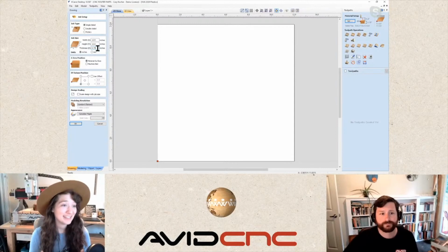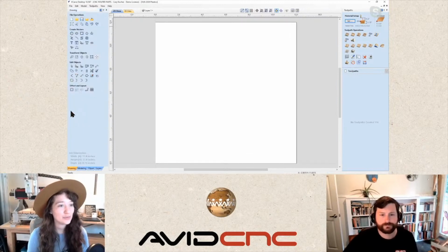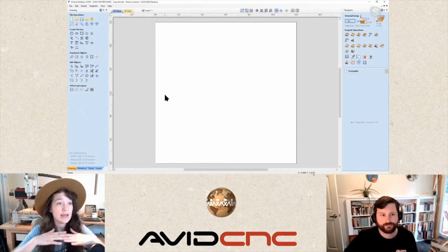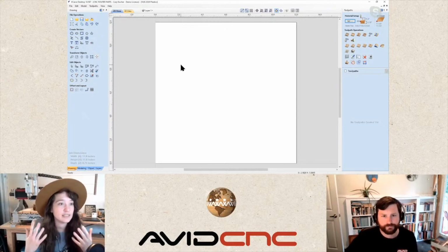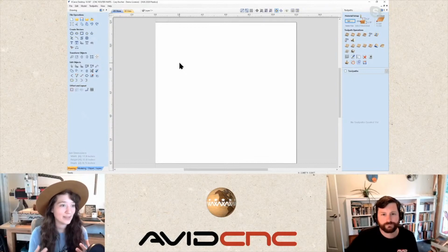Acrylics and plastics are very predictable in terms of thickness. There's a very tight tolerance there. Do be sure, depending on the thickness of your acrylic, there will be different qualities to that surface. For example, if you have a thinner acrylic, there will be a lot more flexibility versus a really thick acrylic like 3/4 inch, which is going to have a lot more stability and not be so subject to lifting from an upcut bit or something like that.